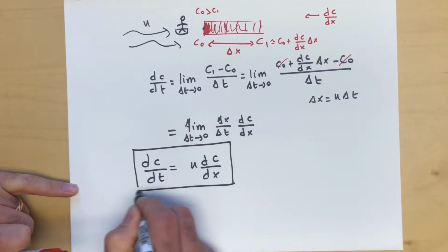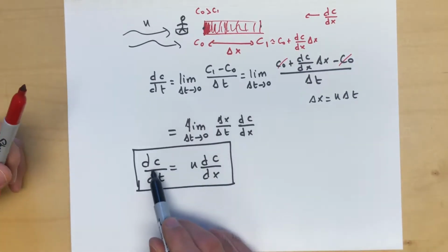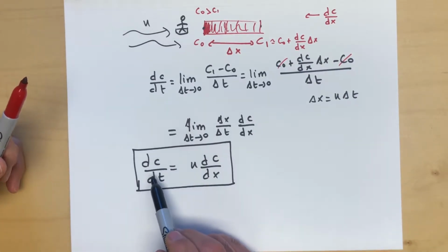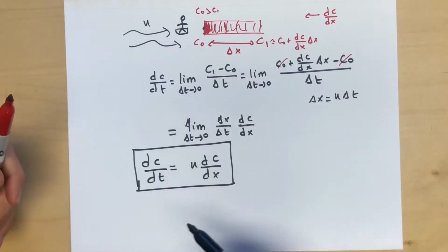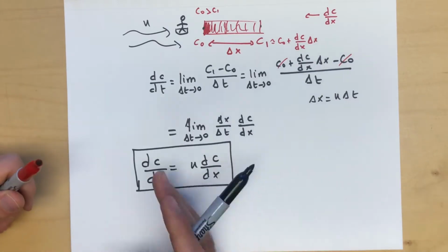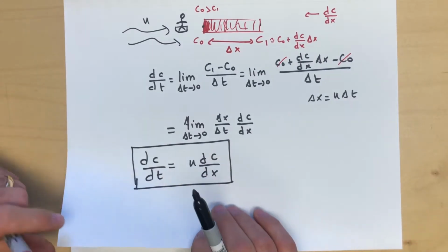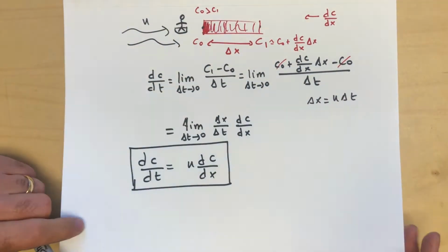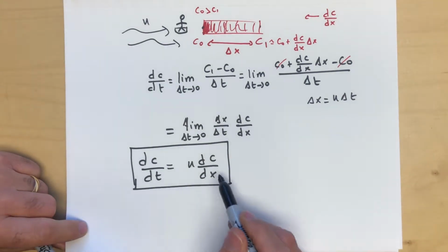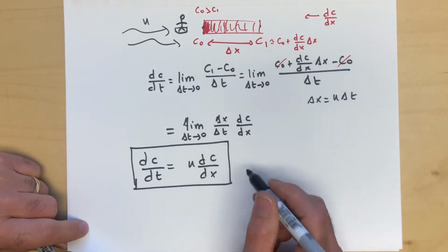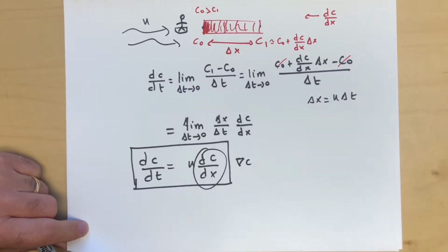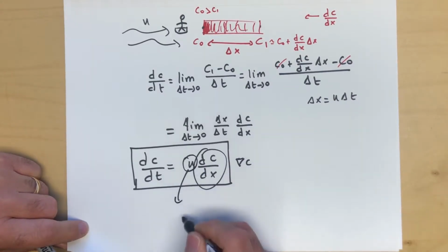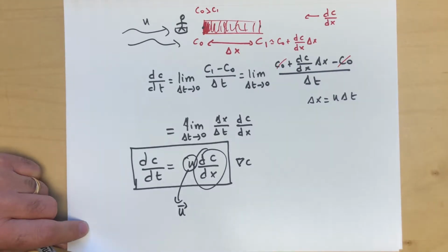And there you go. This is the relation between what the person in the Lagrangian frame is measuring compared to the actual distribution of the concentration gradient. Okay. So now you can see how easy it is to extend this to 3D, that this actually turns into a gradient of the concentration, and this actually turns into the velocity vector field.